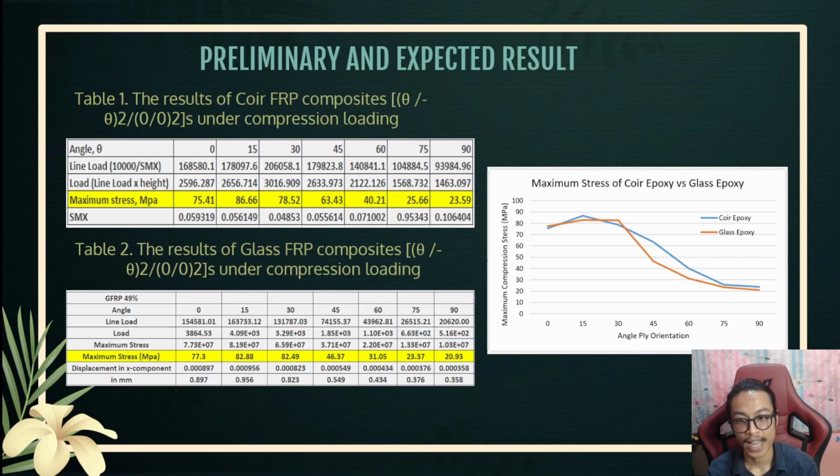This suggests that as the fiber orientation shifted to a higher angle, the compression strength of the composite becomes more dependent on the strength of the fiber matrix interface, thus showing the importance of the properties of the matrix in use in the composite.